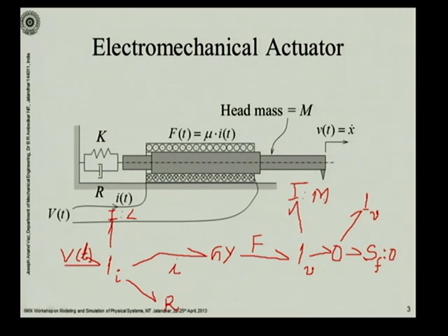So what should we place here? Yes, we should place our stiffness and damper elements, and the relative motion across both of them is the same. So we can assign it here itself. So we can assign the C element here and the R element here. Okay. Here, of course, the modulus of this gyrator is mu. This is our bond graph. It's slightly different from the previous bond graph.